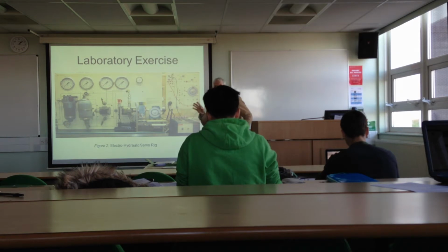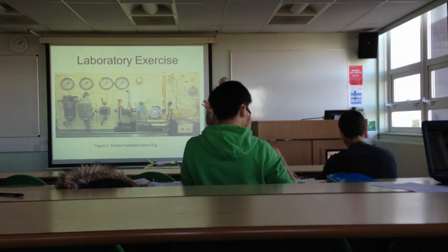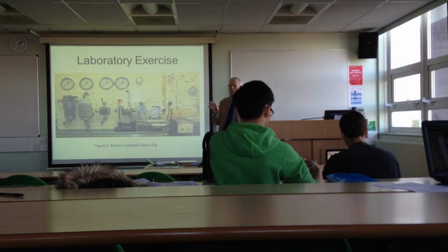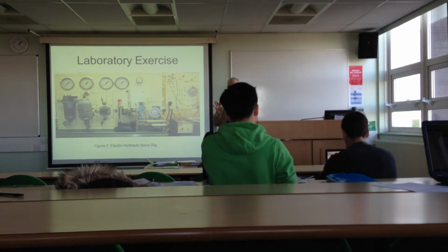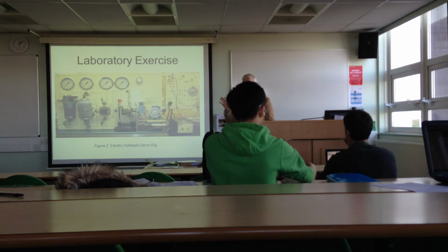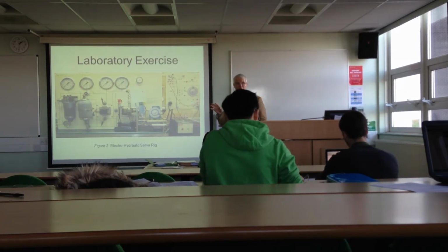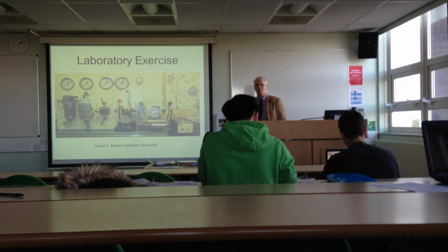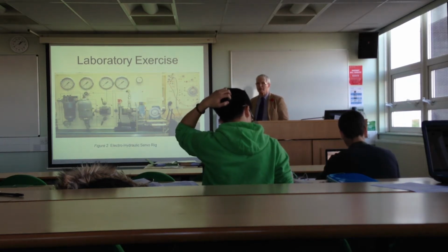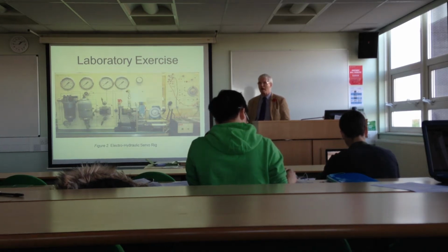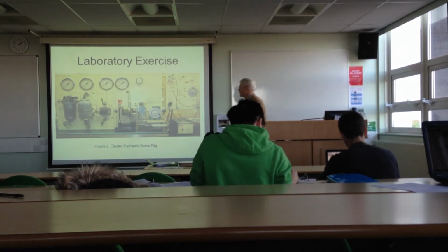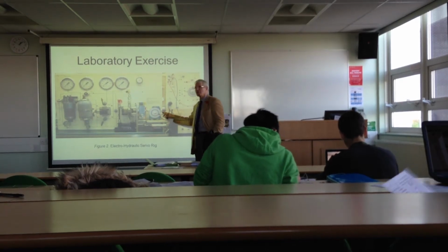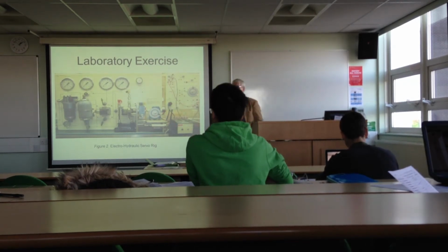Because we're looking at electrohydraulic systems, and I've asked you to look into fly-by-wire, it's fairly clear, I'm sure, as soon as you start looking at fly-by-wire, or you look at the specification of modern aircraft, both civil and military, that they rely entirely on computers. So the pilot is just one of the inputs into the system, and a lot of the inputs are feedback from transducers or encoders. We've got one on here, which is a rotary, we call it a tacho generator.